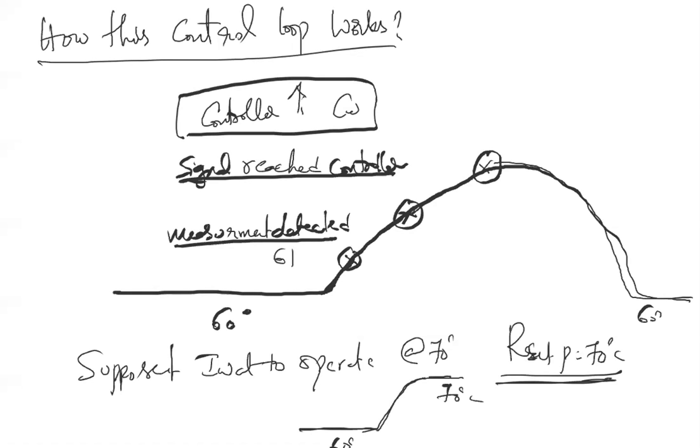So this is what happens when a disturbance affects the system. Because of some disturbance, the process variable has started to deviate and then the controller has brought it back to 60 degrees because you have given a set point of 60 degrees. Suppose my field signal is 60 and my set point is 60, does the controller take any action? No. The controller comes into the picture only when there is a disturbance. So this is what is called regulator mode of the controller.